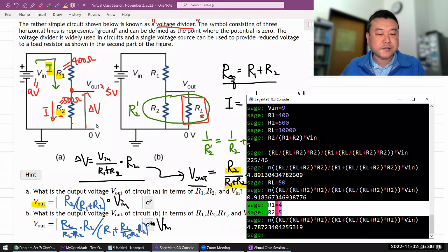So in real practical circuits, when you need to go to a lower voltage, you only use a voltage divider for that specific purpose when you are in a low power situation. With active circuits, semiconductors, operational amplifiers, transistors, there are more efficient ways of doing it.